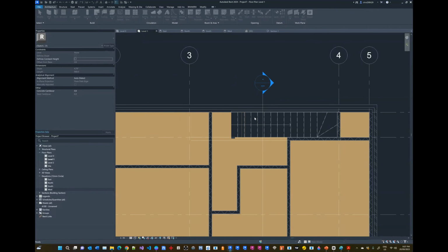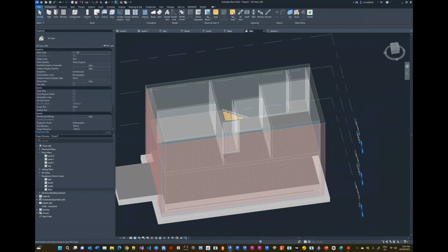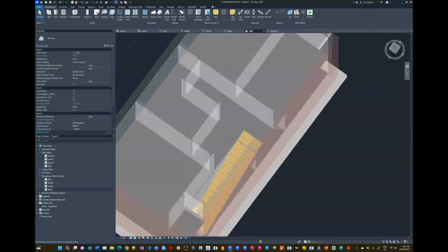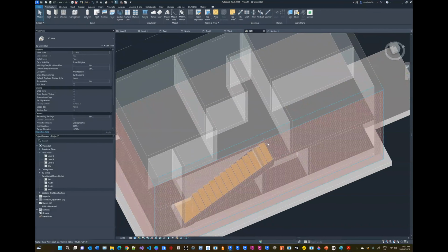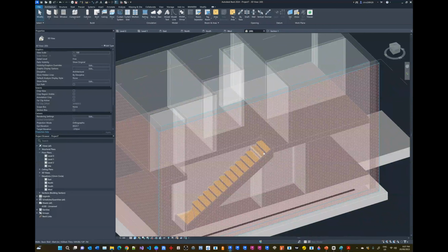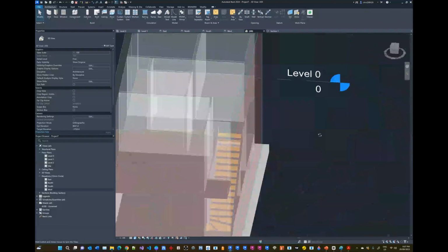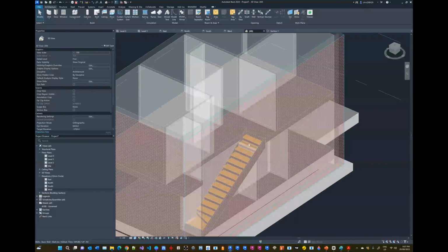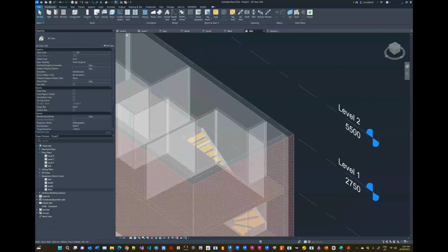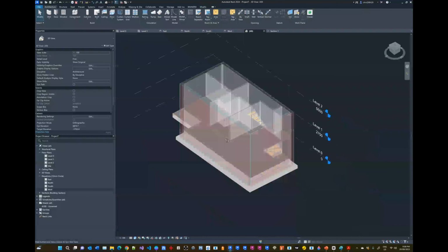it's going to bring this back, and we should be reaching the landing right there, which is absolutely perfect. So we've got our stairs coming up here, reaching that edge, and it's coming in. Okay, notice we've got these stringers running down and it's intersecting here with the floor. We can remove the inner stringer. We don't need it. That'll probably go into the wall, or the stringer could sit inside of the wall. So if we really wanted to, we can start removing those as well from the model. For now, I'm just going to leave them.